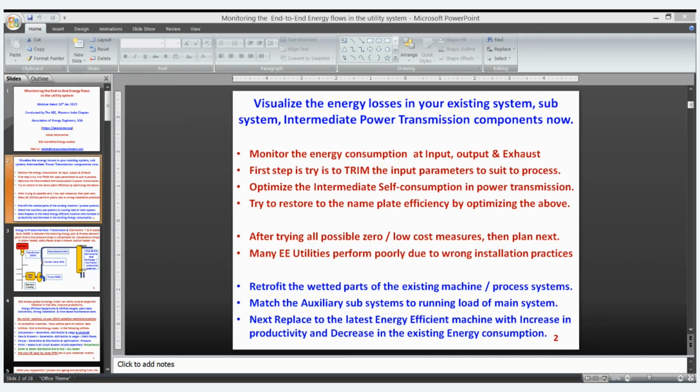So if you see all the inputs, the Bureau of Energy Efficiency has told only one point: monitor the energy inputs of each and every machine above 10 HP running for 2 shifts a day. But now the power tariff has gone up, so we are trying to focus on above 3 HP. If this is monitored with both the kWh meter and the run-hour meter, especially in a batch processing industry, this will definitely help us.